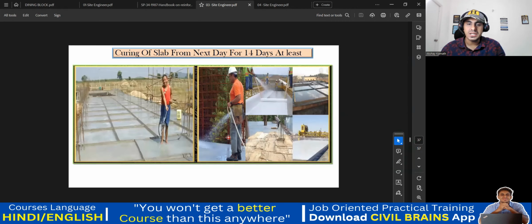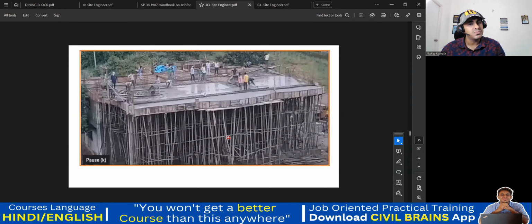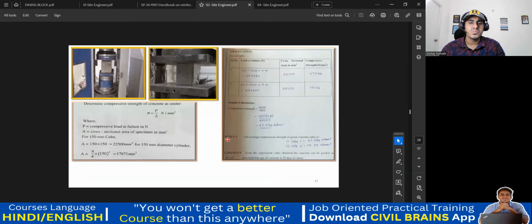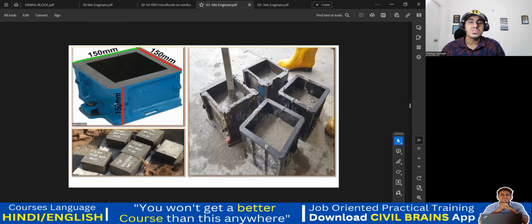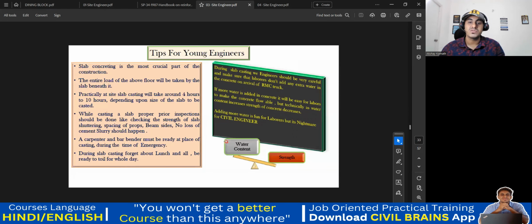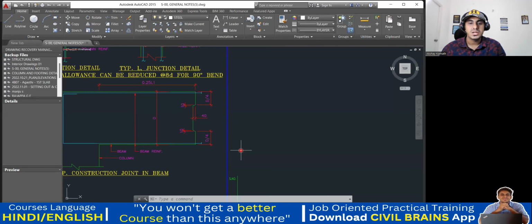So practically, you are supposed to follow all these things, but again, very few people follow this. Even if you cannot give this depression, at least stop the concreting at the point of contraflexion. That you have to keep in mind. Understood? Chalo. I think this also understood.